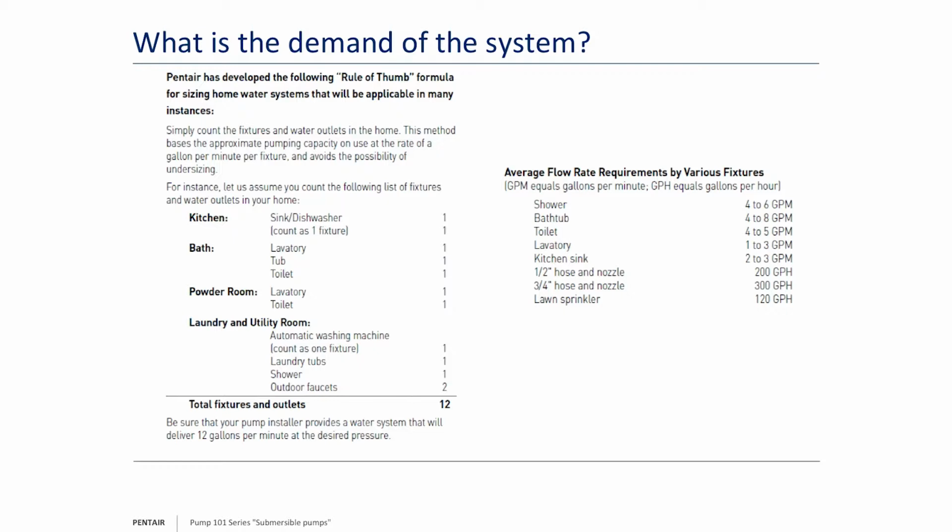Now here's the opposite side of the coin. This house is owned by a family with 5 young children. So there's 7 in the family. Would 12 gallons per minute possibly be enough for all they want to do at this vacation home? Might not. So again, that's why I tell you, it's kind of like horseshoes and hand grenades. We'll get you close, but I won't promise this is a proper answer. You have to know your customer and your customer's needs. So in this example, if the customer is a young family of 5, I might put in a 20 gallon per minute pump. So again, there's your discretion.